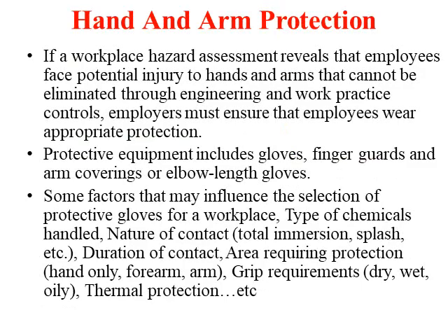Next, safety equipment PPE, we have goggles. As already discussed, there's a difference between a spectacle and goggles. Goggles are tight fitting eye protection that completely cover the eyes, eye sockets and facial area immediately surrounding the eyes, and provide protection from impact, dust and splashes. The application of spectacles and goggles are entirely different. So we should know when to wear a spectacle and when to wear a goggle for any particular operation.